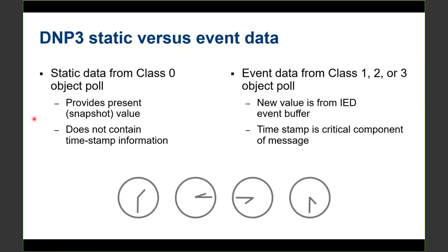I like to repeat this point about not clearing the buffer on the relay, because in many cases we saw problems where customers set up the master station just to poll class 0, because using class 0, the master station is able to get the whole DNP map, and it's pretty easy to set up, right?